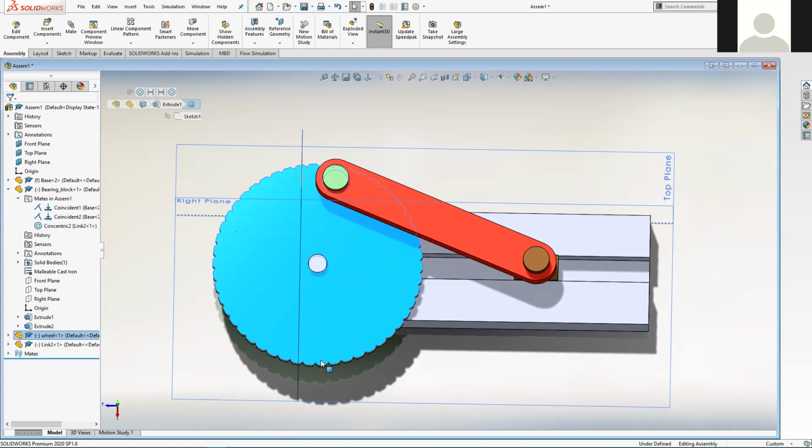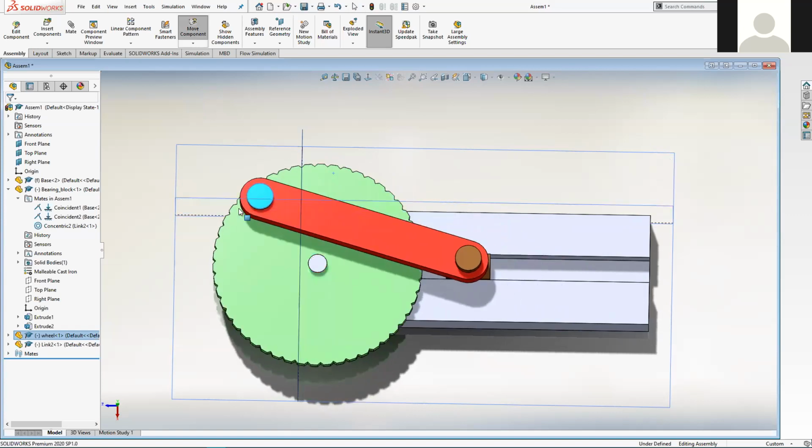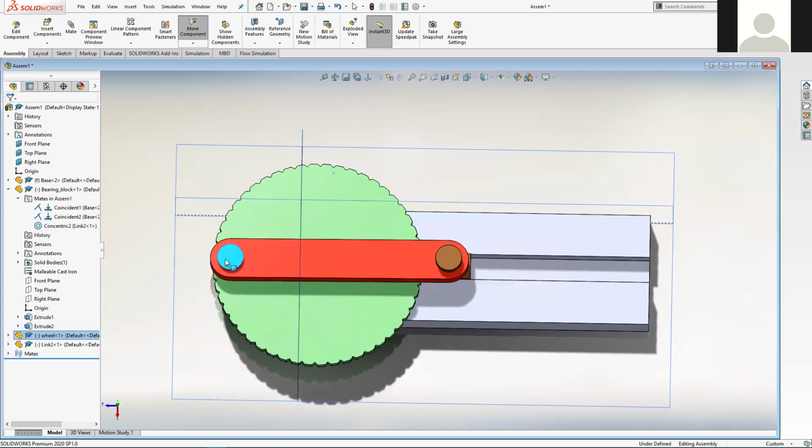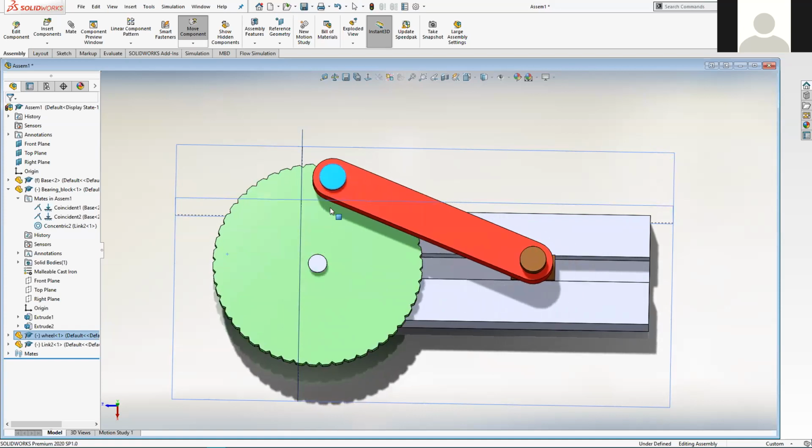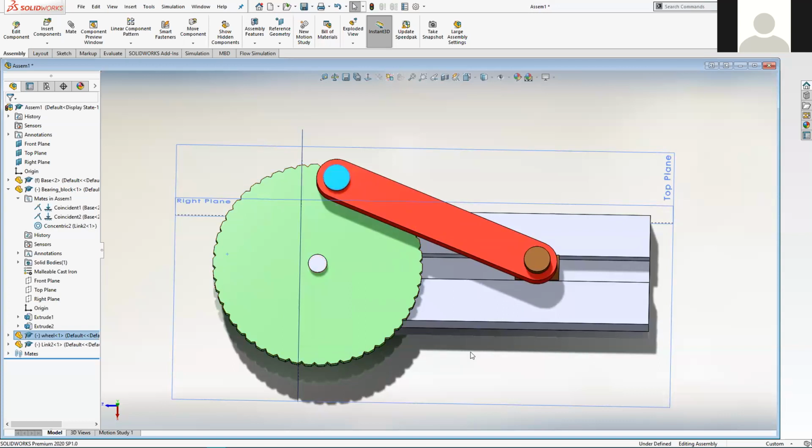And the calculation side of the motion section in SolidWorks has more problems when the bearing block is at one end of its limit of travel there. So if we start it there, sometimes it throws a bit of a spanner in the works. I could investigate why that is, but take my word for it. Put it halfway along, and it will present fewer problems to us.